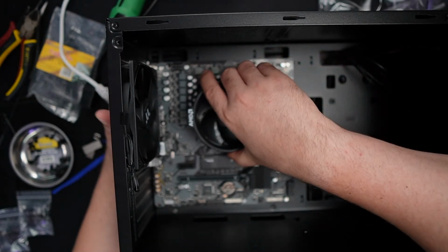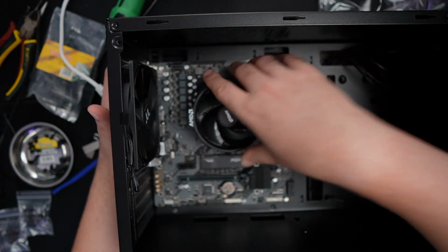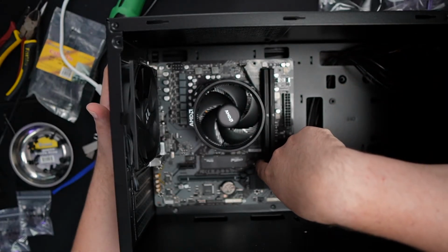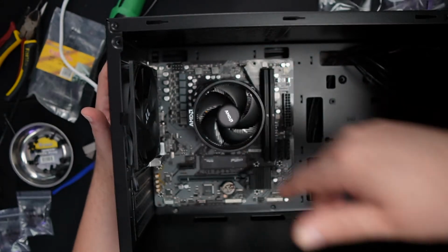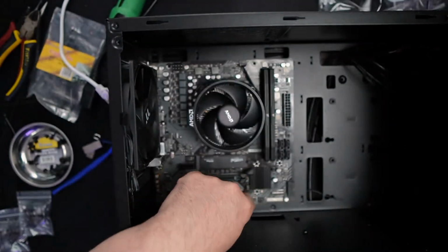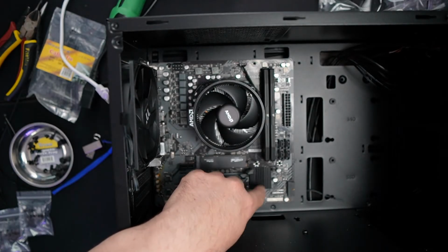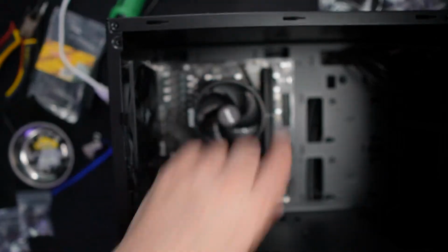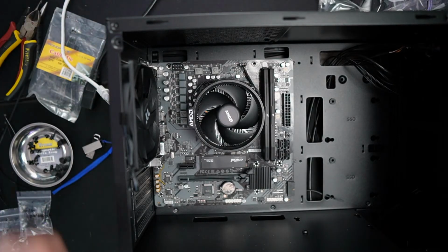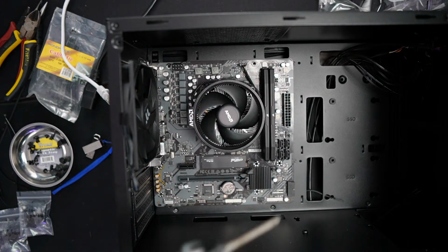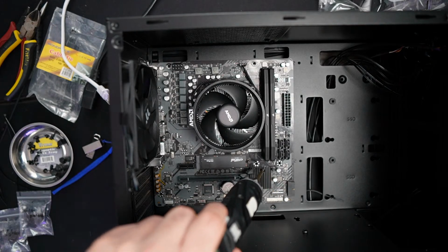All right. Putting this back in place, you're just going to slide the motherboard in, and it's going to latch onto these little standoffs. That just makes it a little easier so that you can put the screws in. If you hear it click in place, you should be able to hear it click a little bit, and you should be able to see all the black standoffs underneath. Now again, just count out your screws. If you have 6 and 6 standoffs, you're good to go. If you have 5 screws and 6 standoffs, take the motherboard back out. You obviously missed one, or maybe one's not needed under a certain area.